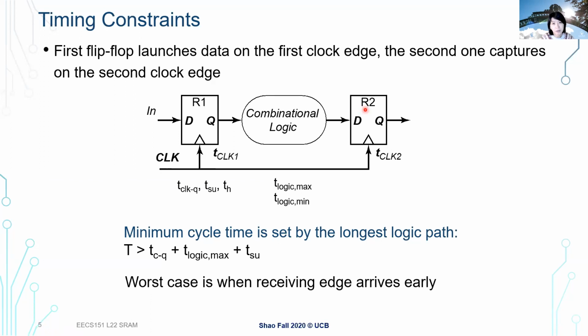So we have talked about how our clock period needs to be greater than basically the critical path of our hardware, right? So you need to make sure that all the signals can actually propagate through. And in that discussion, we have our clock period here. All the signals need to be propagated through correctly, not just for the combinational logic, but that also includes what we discussed earlier, the flip-flop before our combinational logic and also the flip-flop after our combinational logic.